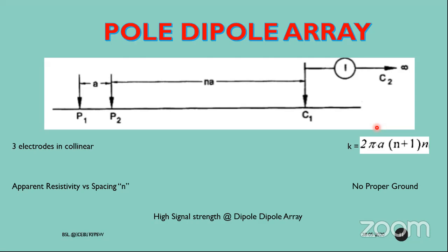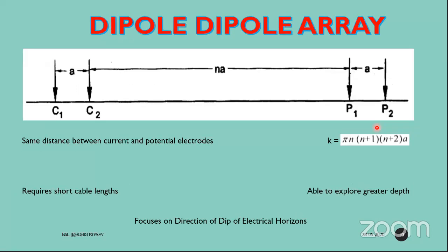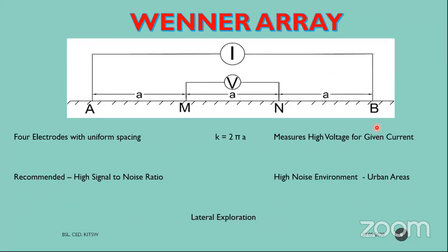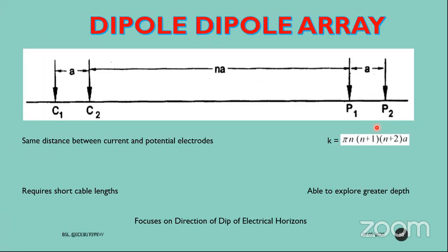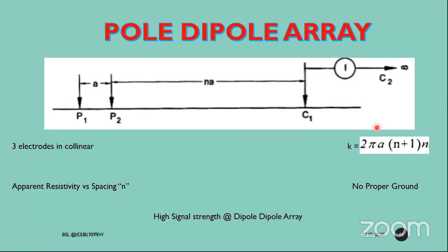So it's very simple. When the array approach becomes sophisticated, if you see the difference between these, Wenner is very simple. Schlumberger is a little bit different. Pole, dipole is a little bit tough, and pole to dipole is much tougher. When the toughness is increasing, then the quality of the image goes on decreasing. If I ask you, if I want only 1D imaging by pole to dipole, the answer is no, you can't do it, because the quality of the image will decrease drastically, and we can't use pole to dipole for 1D.